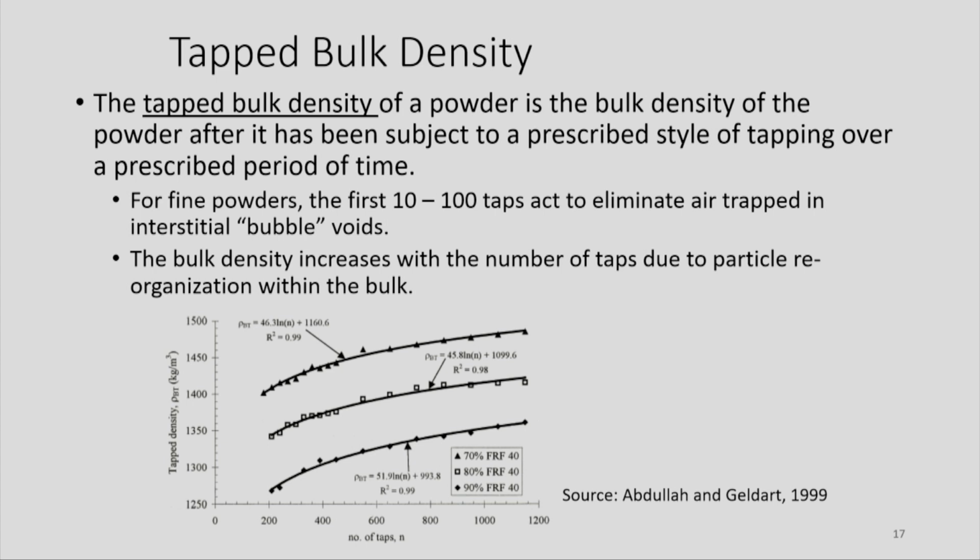So for agriculture students, it's very similar. You put sample powder in a container and then tap it like this. Keep on tapping, the volume keeps on changing. It's very similar if you're loading lots of material in a truck or container. When it reaches its destination, usually the volume goes down, right? Due to tapping, small particles will fill into the large void spaces and the volume goes down. That's what we will be quantifying using tap density.